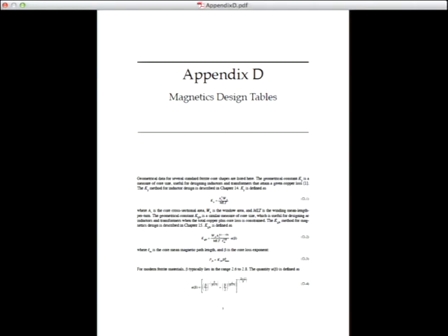But you can make the ferrite core shape out of whatever ferrite material you want, and it's the material that has the core loss equation associated with it. So you can get this shape of core in a good high-frequency, low core loss material, or you can get the same core shape in a cheaper, lower-frequency, higher loss material.